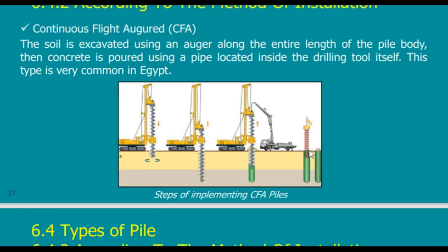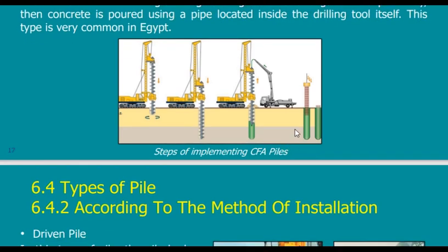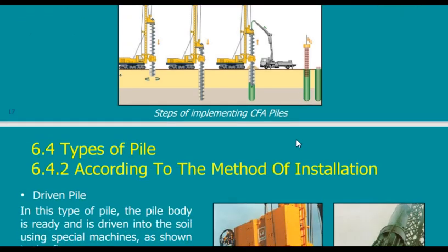So I will have to cut the steel reinforcement at this level, and say this is the end of it. So usually, don't expect in normal sites or in low grade sites that you will have reinforcement reaching more than 4 to 5 meters. In very good sites, you may reach the bottom of shallow piles, but at least the last 2 meters are impossible for the cage to penetrate.